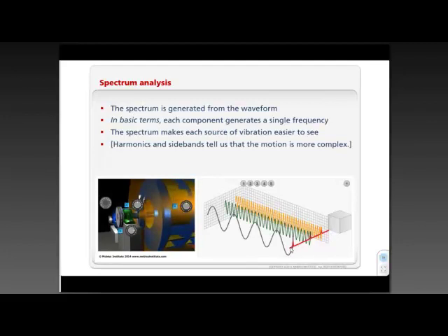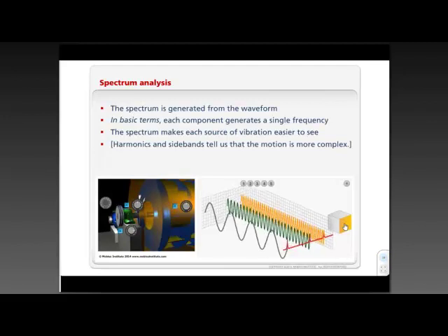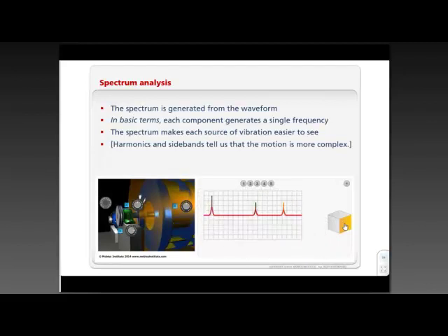Along this axis, therefore, is the frequency. Low frequency from once per revolution and so on. And what I'm going to do now is look at things from this perspective. I'm going to look at the waveforms end on. It's the easiest way to think about what an FFT does. If we rotate that around, there is the spectrum. And you can imagine that behind that one is that grey sine wave, and behind this one is the green sine wave, and behind here is the orange sine wave. In the FFT process, the simple way to think about it is we're cutting off the bottoms. It's a little more complicated than that, but that's what you're looking at with the spectrum.